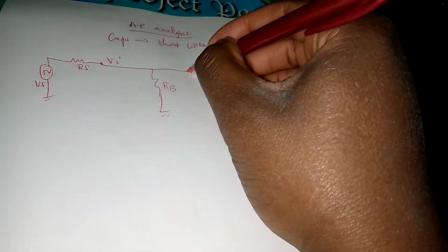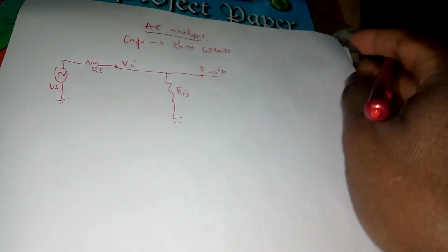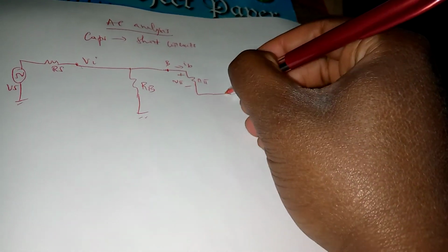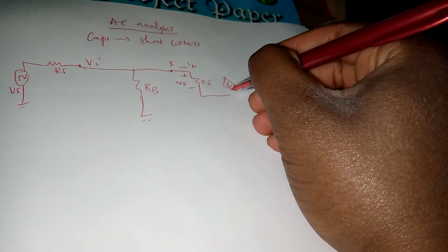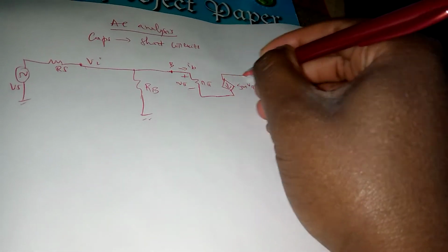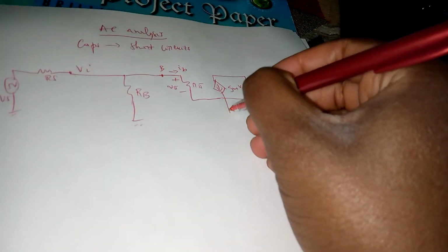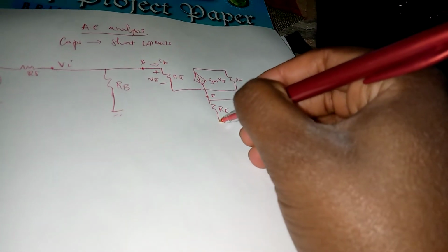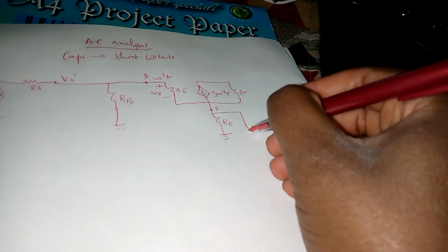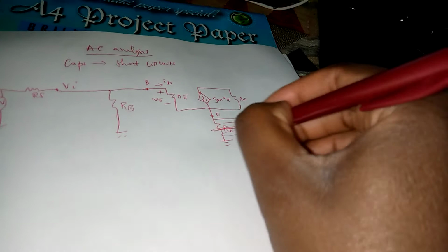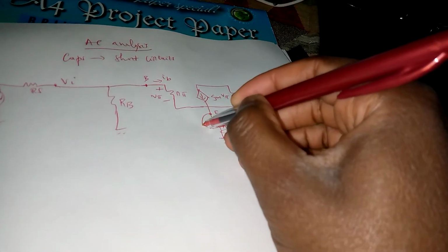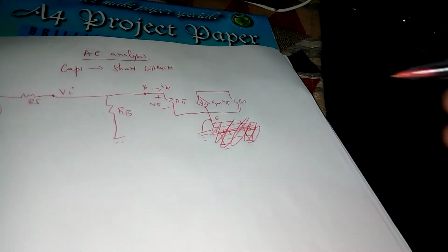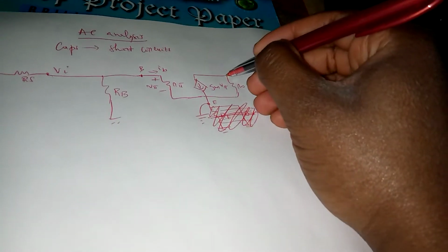Then we enter the transistor through the base, we've got IB flowing there. Got r pi, got plus minus v pi. Then, it's NPN, so gm v pi in parallel with ro. Then we've got the emitter here, and as we go to the emitter, we're supposed to have RE, but now the capacitor behaves like a short circuit, RE all the way to VEE, which becomes ground. Capacitor becoming short circuit all the way to ground. 0 ohm in parallel with RE, so that capacitor will bypass RE. So we end up having that emitter just grounded.